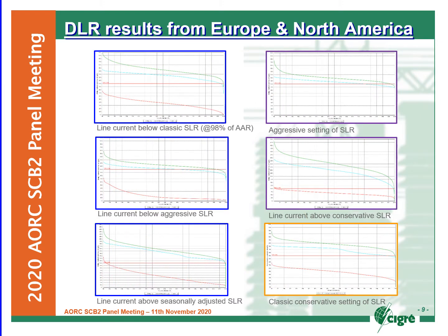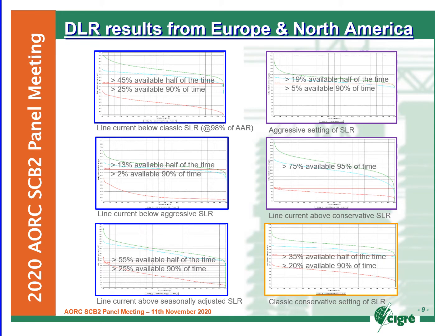Now we see the same systems, but with the ratings and line loadings in the form of duration curves. Here you can see that the characteristics of the green line in relation to the blue line is the same for all systems. Wind cooling releases overall extra capacity compared to just the ambient cooling. From the observations here, as well as the 70 other systems we have in operation around the world, we see that typically at least 20% of extra capacity is available most of the time.